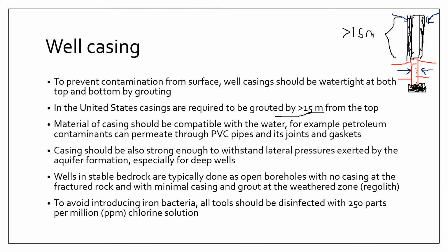Now, when we are talking about wells in bedrock, there are wells that might not need any sort of casing. These are what we call open boreholes. And in open boreholes, we typically just grout the weathered or the regolith zone to prevent the entrance of water from the surface.